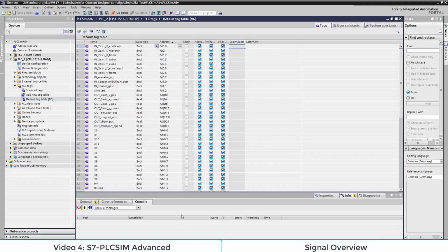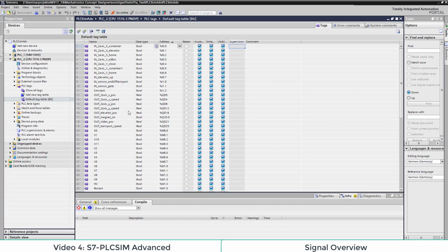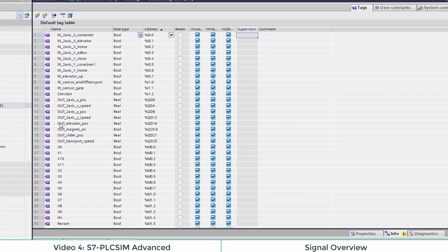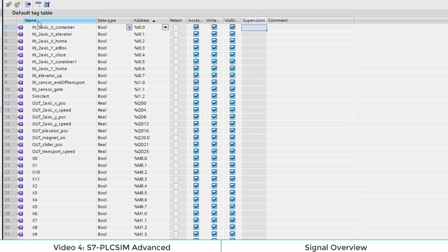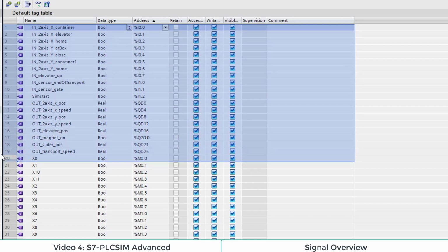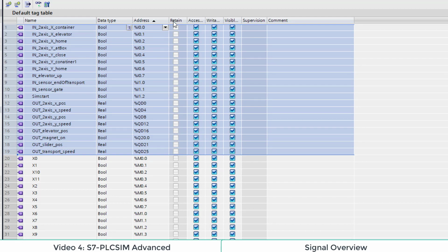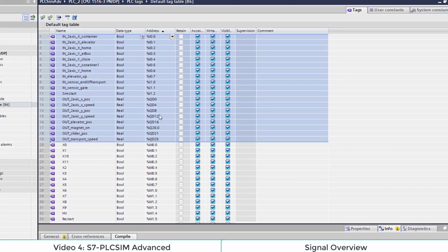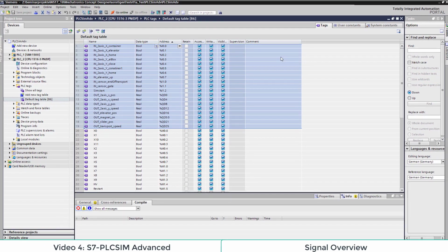In TIA-Portal, we have inputs fitting to the outputs of MCD and outputs fitting to the input of MCD. We named those objects accordingly. This is good for clarity in programming, but automapping doesn't work with this naming. Automapping only works for signals that would be named both in MCD and TIA-Portal the same. Instead, we will map manually.